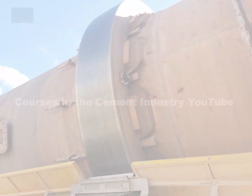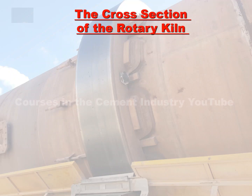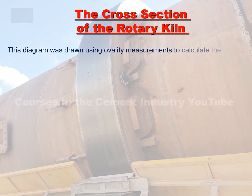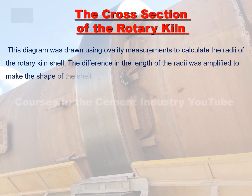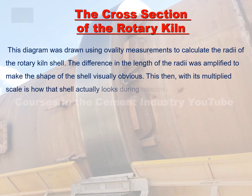We follow together the analysis of the cross-section of the rotary kiln. In the previous slide, this diagram was drawn using ovality measurements to calculate the radii of the rotary kiln shell. The difference in the length of the radii was amplified to make the shape of the shell visually obvious. This then, with its multiplied scale, is how that shell actually looks during rotation.